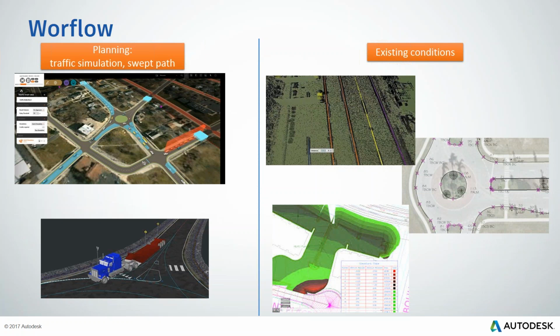And also you have to realize that if there is a detour, maybe heavy trucks will go a different way, to roads which are maybe not really designed for such heavy vehicles. So what needs to be done is to check sweep path analysis to be sure that these trucks which are normally passing through this rehabilitated road can go through these side roads and they will not make damage to the city furniture, traffic signs, etc. So then I will speak about existing conditions.